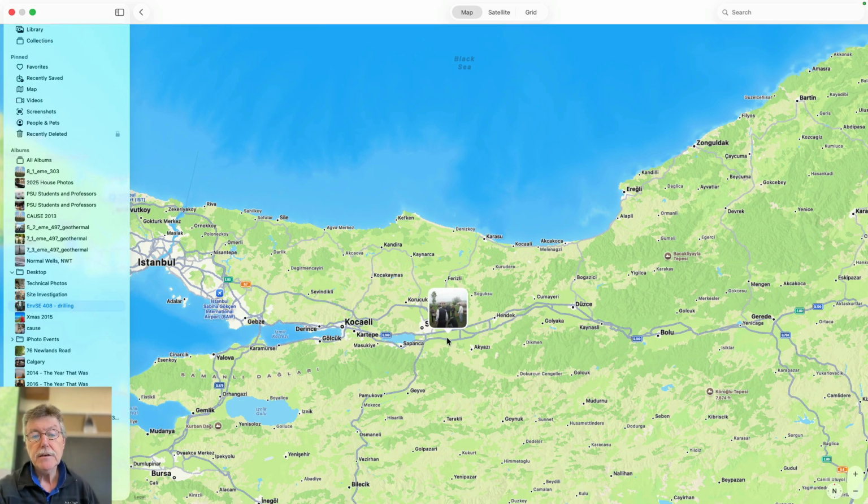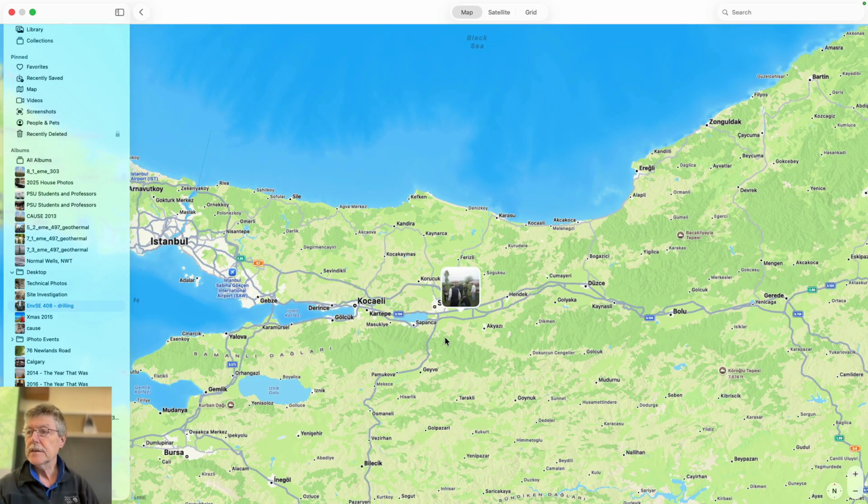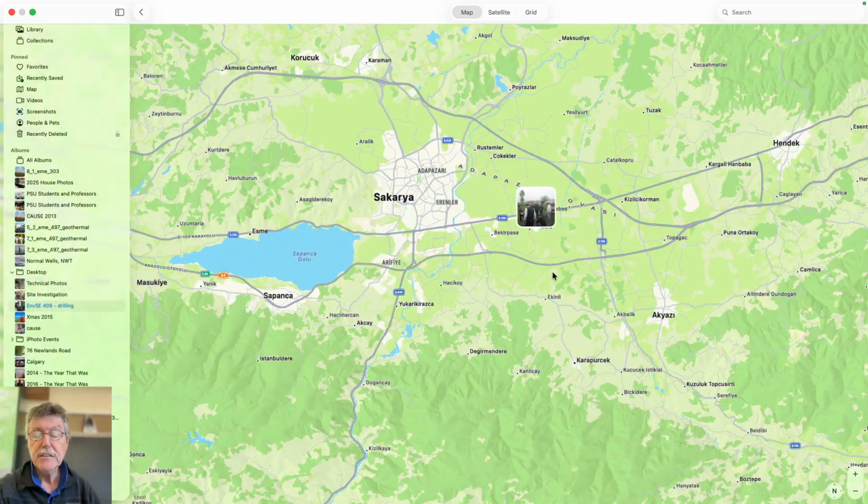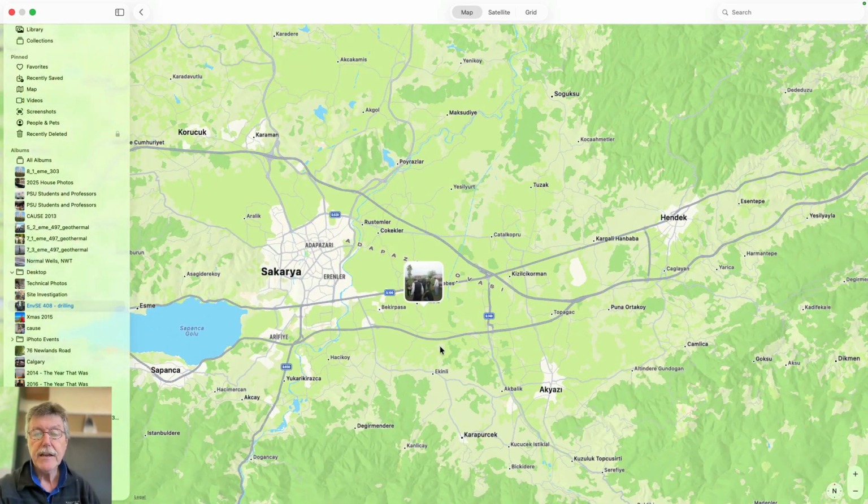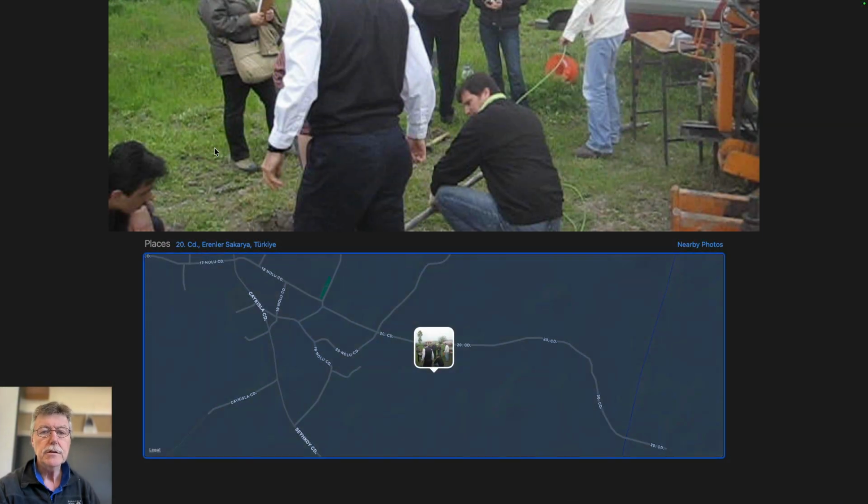And so the big question here is that it killed people by liquefying sand, which instead of being solid became a slurry, and buildings would fall over and sink in it, and septic tanks would pop out because they're buoyant in this slurry. So this was to investigate, kind of understand the mechanics of liquefaction to be able to see how to solve that problem so buildings don't liquefy. And the Anatolian fault must run across here. It's the same one that kicked off in Syria in February 2 years ago, I think.